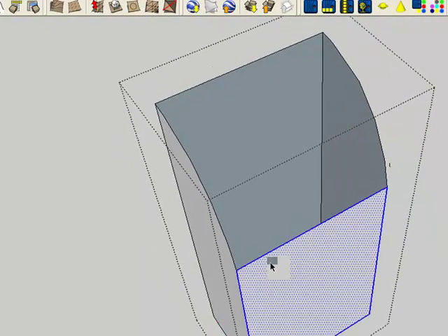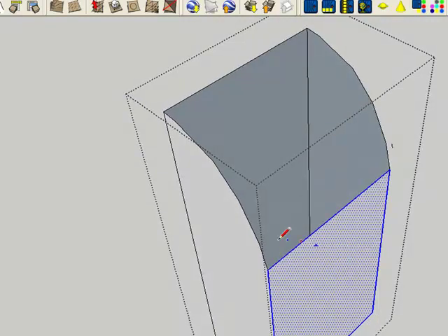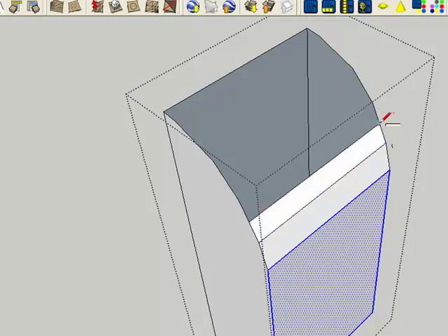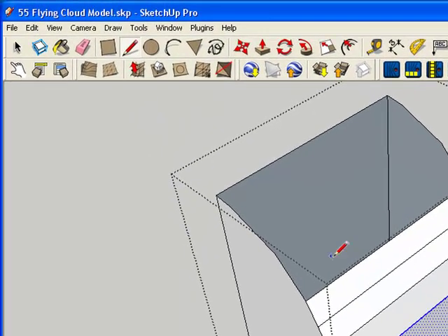And now I should be able to take my line tool, which is the L key, and connect these points back up. And see, I have to find the green point. Or you can also use, which I just did there, the blue point. See, here's the green point. There's a blue point inside, which is actually the middle place between where this is.